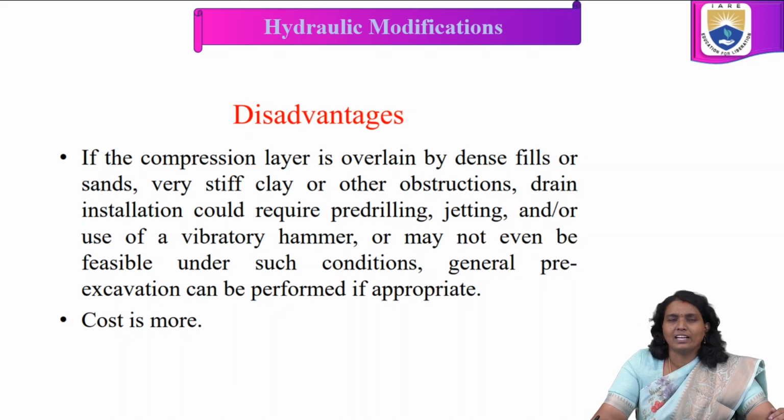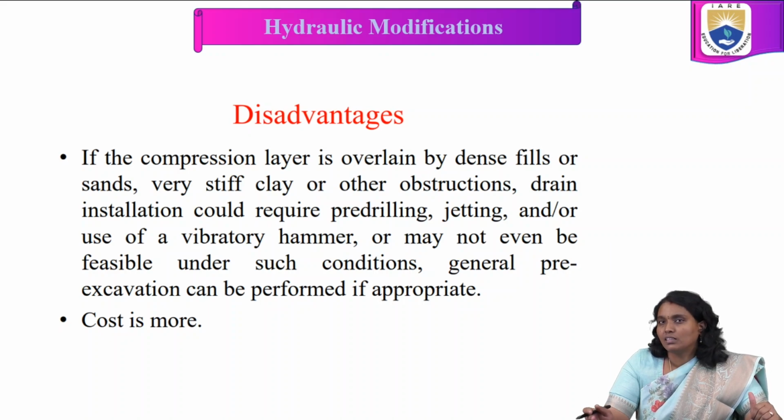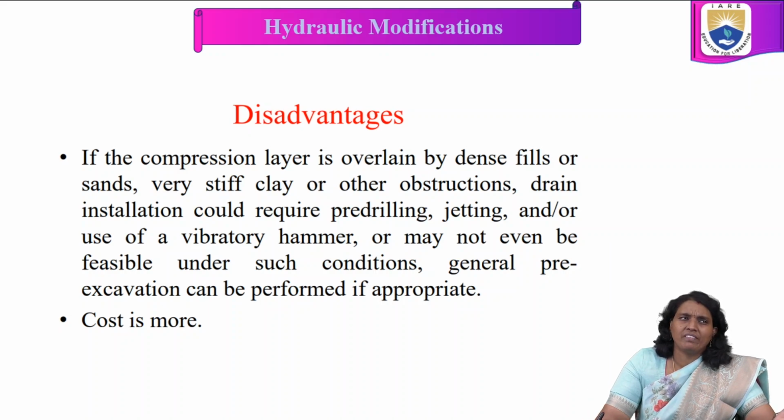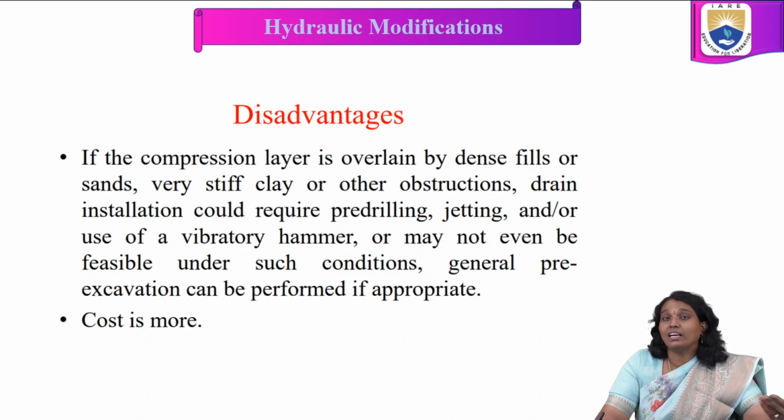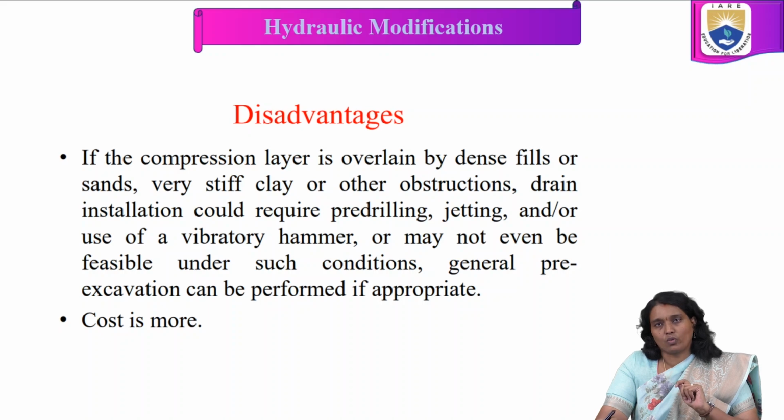So in some conditions they are not adoptable for the location where we require enhancement of the soil properties. With these kinds of disturbances, PVD drains are highly difficult to install. It takes lots of time and pre-work is required.